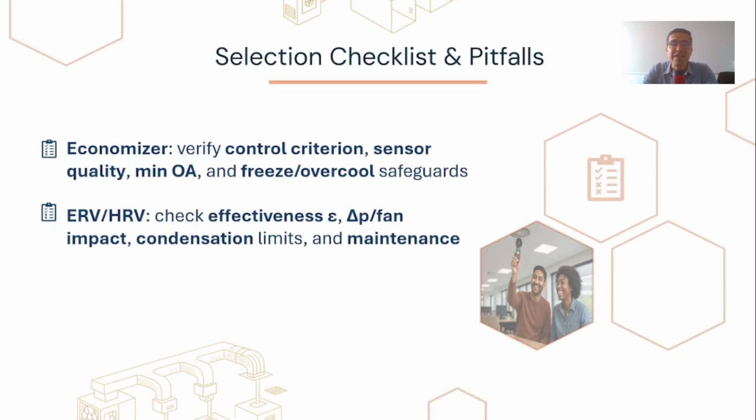For instance, in colder climates, condensate can freeze in the HRVs, whereas ERVs are generally more effective at handling moisture. If you have warm outdoor air that is going to be cooled at these HRVs, then you are going to have some condensation, and it could be even worse in colder climates, where you can have freezing.